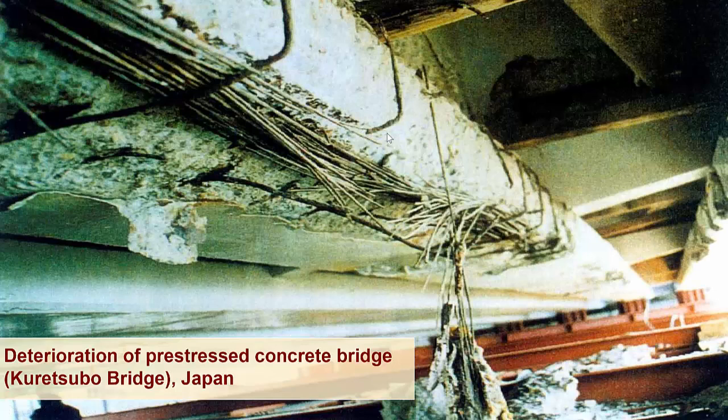This is an example of a pre-stressed concrete bridge in Japan. The bridge is located near the ocean, so it is a very extreme marine environment. Especially for structures like reinforced concrete structures, in the marine environment, the salt in the ocean can lead to the corrosion of the reinforcements or the steel inside the concrete, and that's what happened in this bridge. As you can see, the concrete has come out, and the steel inside it is a pre-stressed steel that is exposed to the elements, and it started deteriorating, it started corroding, and once the steel breaks, then the structural integrity is compromised. So they had to completely demolish the bridge and construct the new bridge. So this is what happens when the structure does not meet the durability requirement.